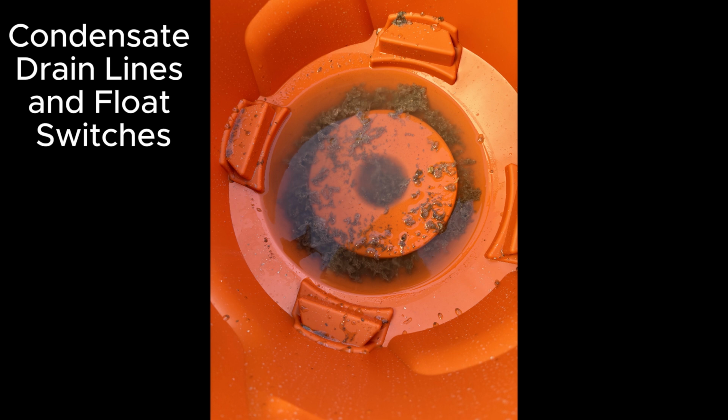That is something that you can do. I do it as a technician whenever I get a call for thermostats turning off. A lot of times it's a clog in the condensate drain line, and you can see you can get all this gunk out, and it will turn your thermostat back on.